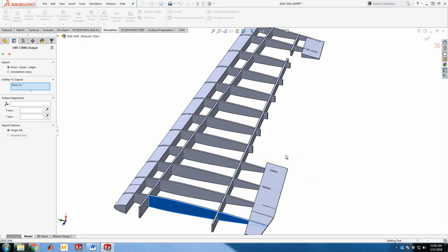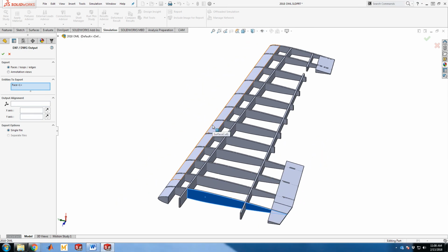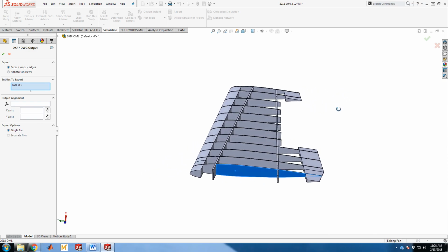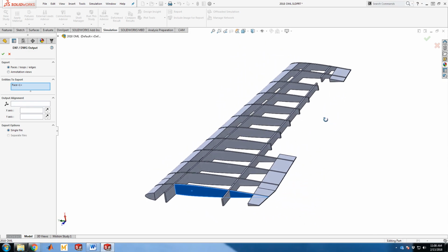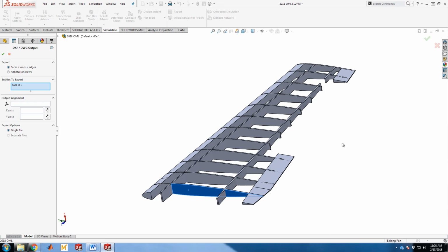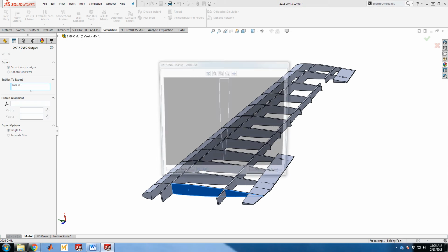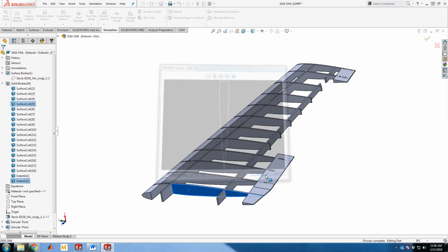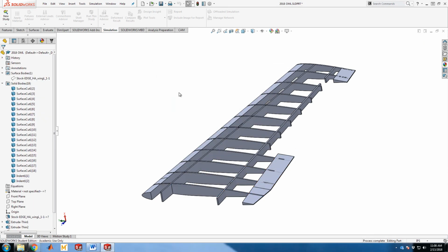So becoming proficient with SolidWorks, becoming proficient with any CAD program, it's just that SolidWorks happens to be the one we have on campus and the one I like teaching from, certainly saves you a lot of time. So you basically would export that as a face. That's what you get. Save. There you go. Now you'd have a DXF that you can actually load into a laser cutter and cut that part exactly to the shape and dimensions you see in CAD.